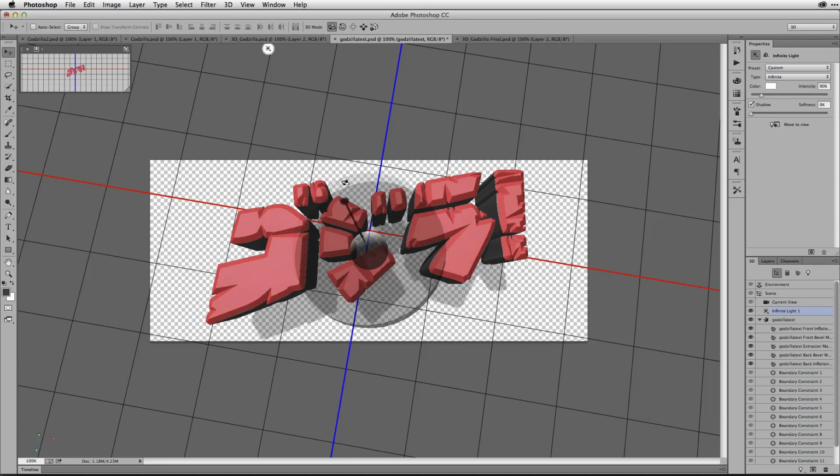But in this case, I want to cast a nice shadow pointing right down onto the surface of my poster. And that's why I moved my camera to look down on this so that the shadow casts onto the ground plane. And we remember that the ground plane is represented by this grid in the background. This looks great. This is a really nice, simple, basic introduction to text. We've extruded the text. We added a detail to the surface of the text, and we moved the shadow.